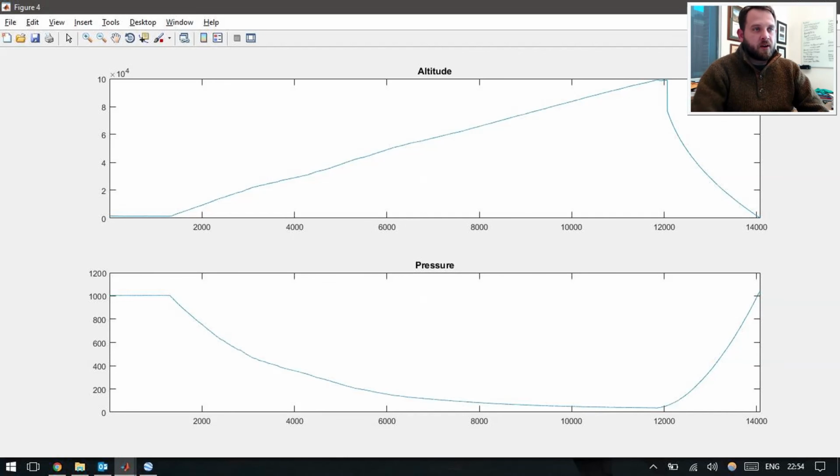Irrespective of the speed across the ground and heading, this is the ascent and descent profile, which you can see from the time of launch all the way up to 99,000 feet. It's almost a perfect linear 750 feet a minute climb. As we're climbing, the barometric pressure begins to bleed off. And you can see we actually reach about half of the available oxygen somewhere between 28 and 30,000 feet.